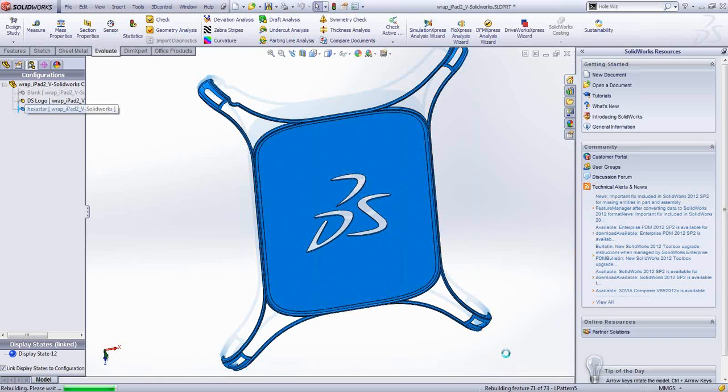We're not even doing anything here. We're not adding anything. We're not editing anything. We're just switching between configurations, and SolidWorks is taking a considerable amount of time in rebuilding this. So we can eliminate all of this wait time by using feature freeze. It has a linear pattern. I think it is updating the linear pattern.